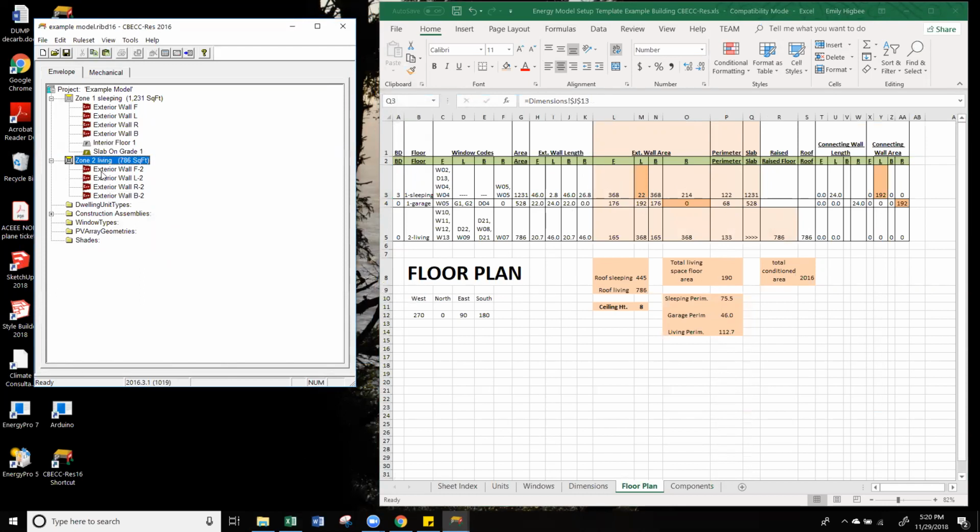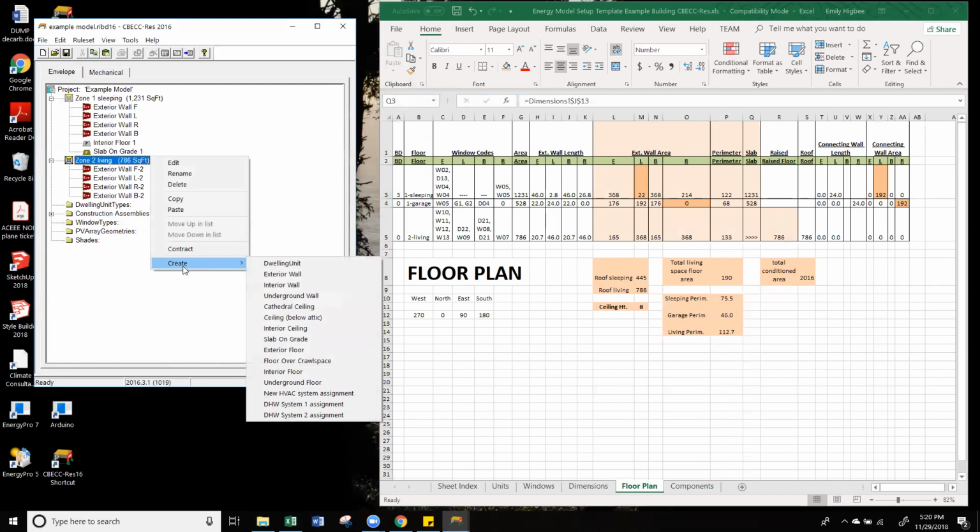Since this zone is on the second floor, it's going to have a ceiling. This is also interesting, which I decided on, I guess, through trial and error as I was building the other model. Looking at the building plans, I'm assuming there is no attic within the building. So basically, I modeled this as a cathedral ceiling, meaning a typical cathedral ceiling, the ceiling follows the triangle of the roof and you don't have any attic. But basically what I did when I created it was made the slope of the roof 0, so it'd be just like a flat ceiling. And that's how I approached it.